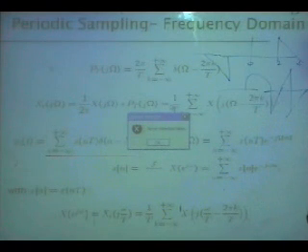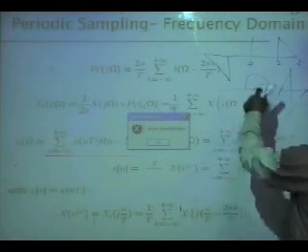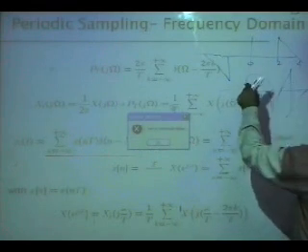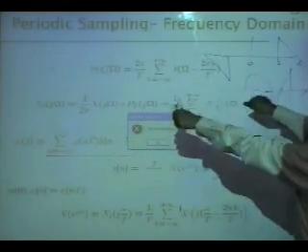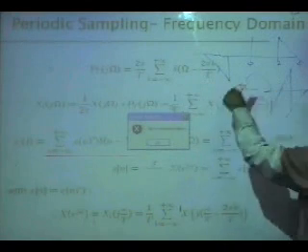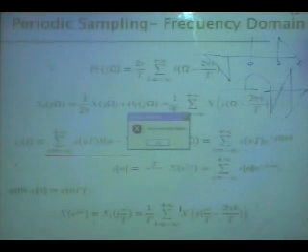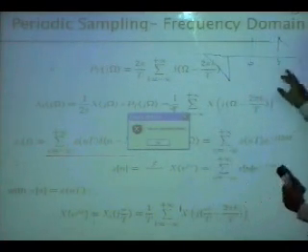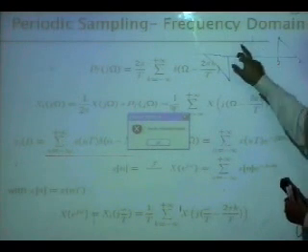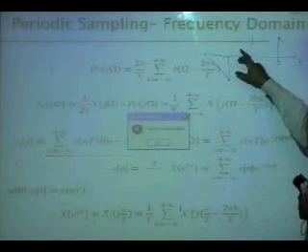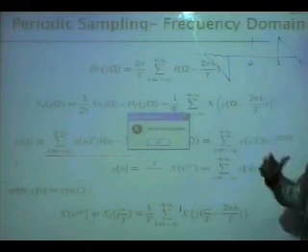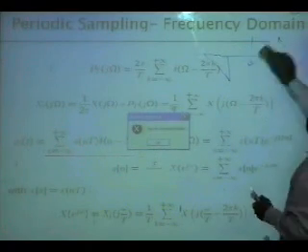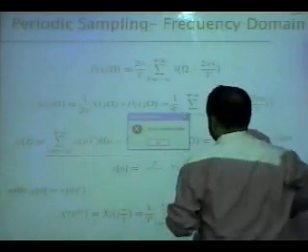That is all you need to remember from this part. If you have to, copy it on a tracing paper, then take it on every omega of s and make copies and find out if there is aliasing. For example, if this is a clean band, you will find that if you sample it at 4, something will start appearing here and here. If you sample it at 2, something else might happen, but that is something you need to remember.